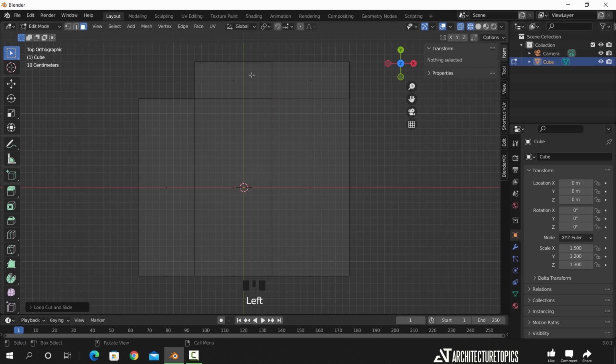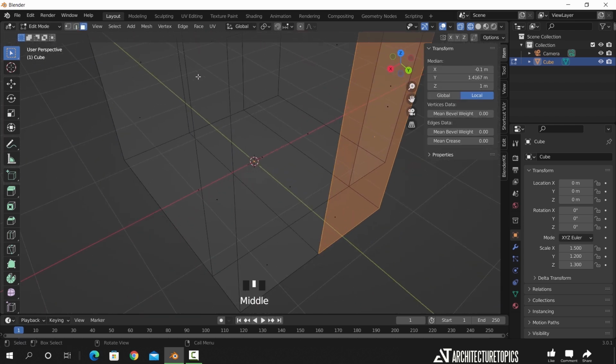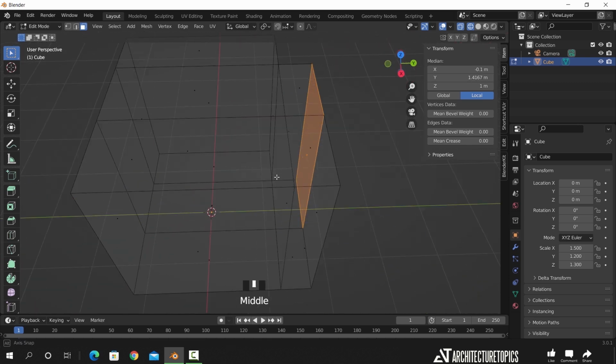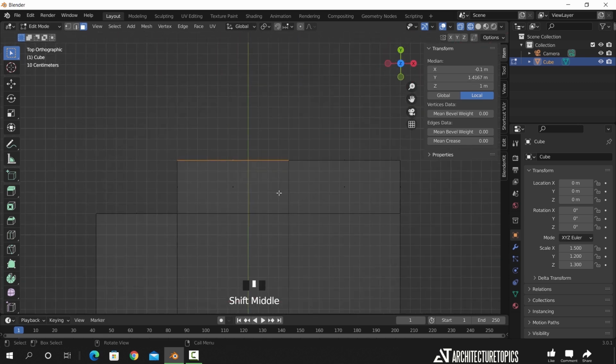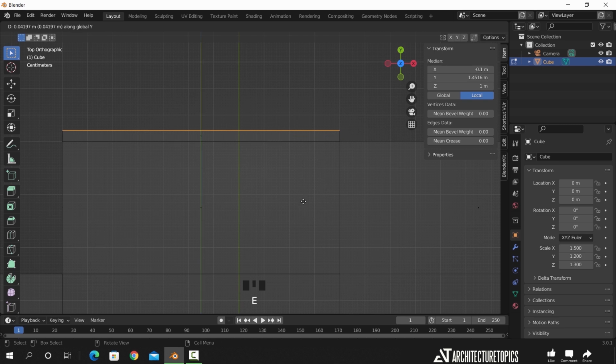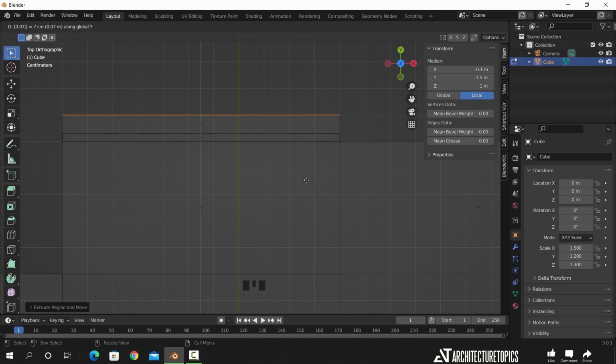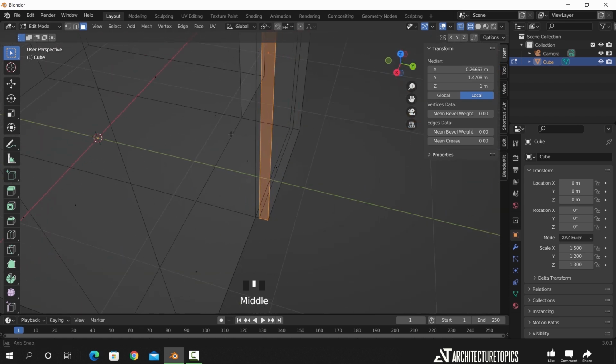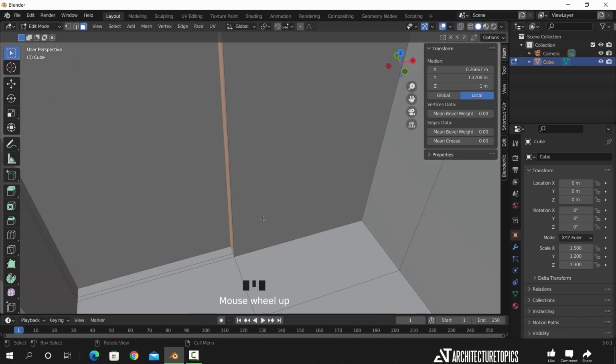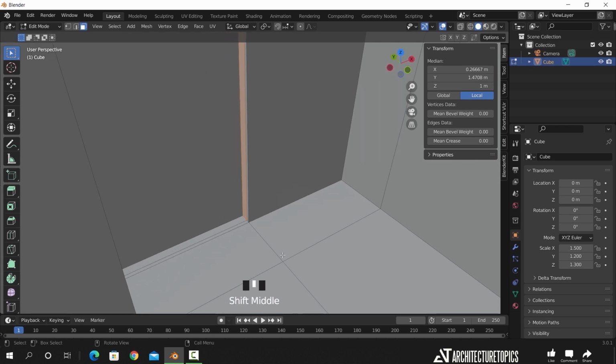We did this to create a small area in the wall for the hidden light, so once I selected this face, I will extrude it a bit to give it a thickness, then we can extrude it again by a bigger amount. With this face selected, hit E to extrude it to the right and make an area for the hidden light.